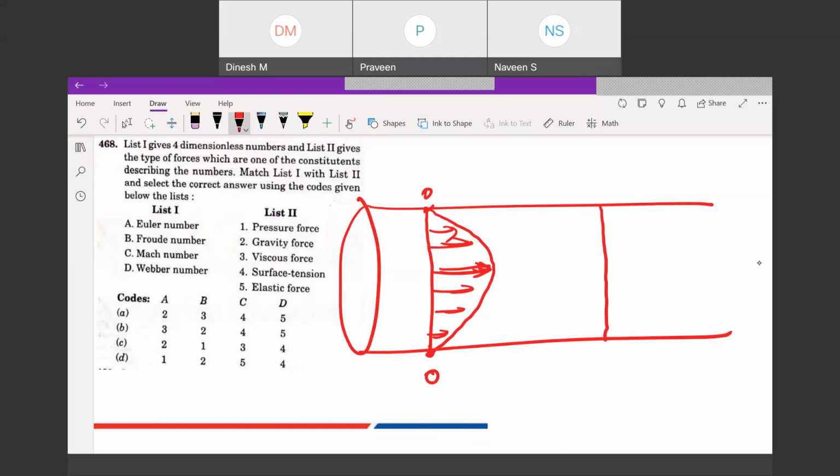It seems like if it is turbulent, it is not uniform. The word itself signifies that turbulent will not be uniform, but it is uniform. Why? Because of mixing only it is uniform. You see, its profile will be something like this. This will be almost flat only.